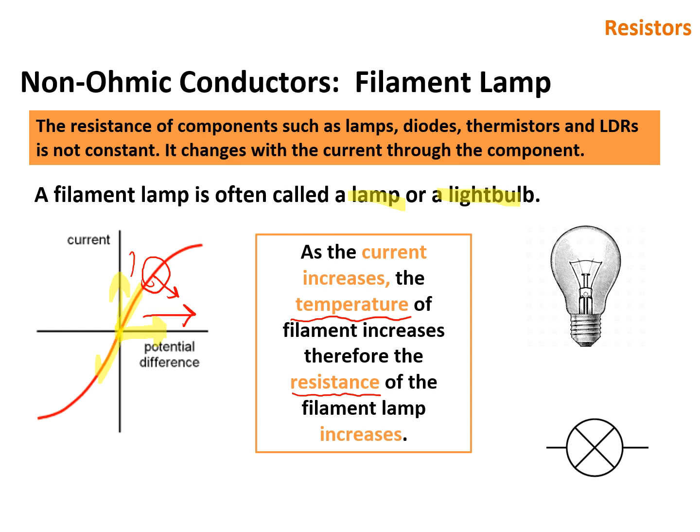The current increases, but not by as much, and that's why it goes from starting off steep, then the resistance is higher, so it doesn't increase as much and as much and as much, and when you draw all those together you get that smooth curve. And at this point up here where I've just finished off that red line, you can keep increasing the potential difference, but no more current can flow through.